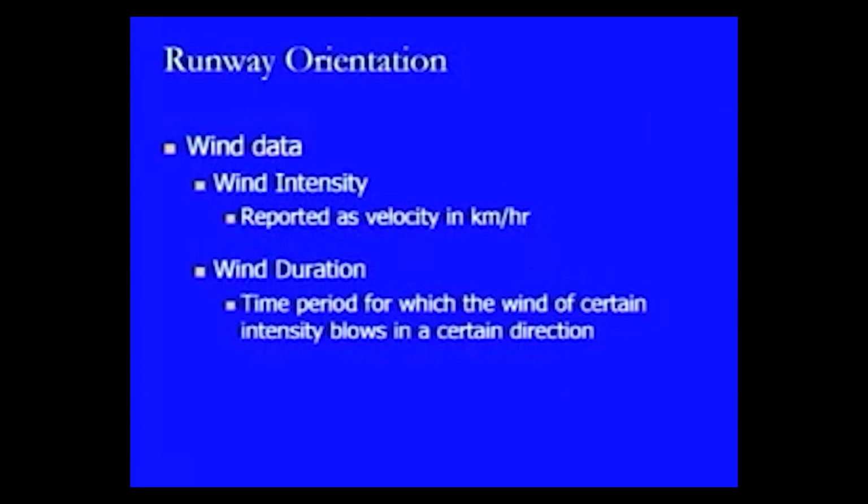Another aspect is the duration for which the wind is available with certain intensity for certain directions at the airport. So, that is another aspect which needs to be taken care of, and this is one of the design parameters which we use while fixing the runway orientation.